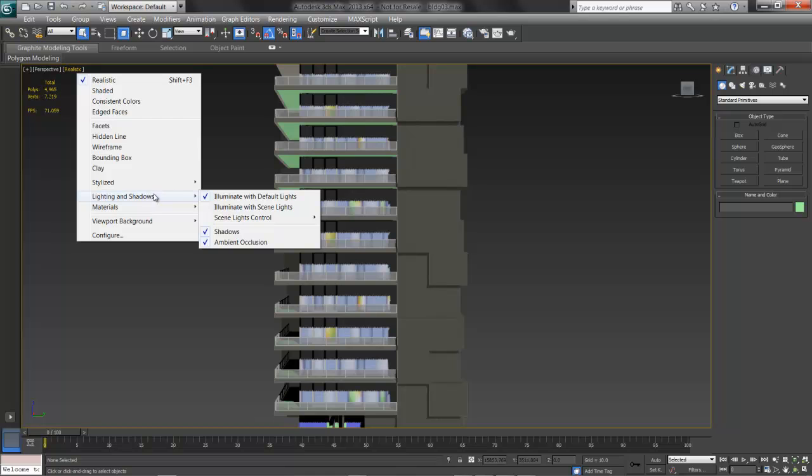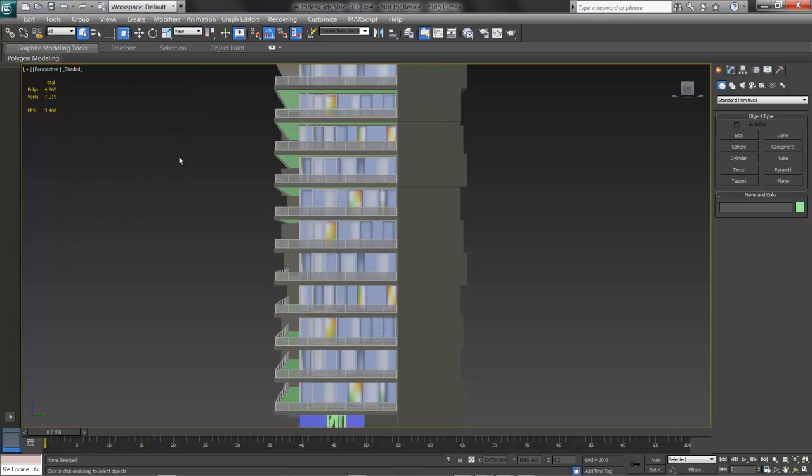We can make a choice here then to show our lighting or simply tone things, depending on what we need to see. We can also choose shadows and ambient occlusion, and this is powered by the nitrous viewports here in 3ds Max, taking advantage of the power of the graphics cards we have available these days and DirectX. I can switch around the views if I need. For example, a shaded view isn't going to shadow, but will light decently, and may provide me a better way of seeing what I need to.